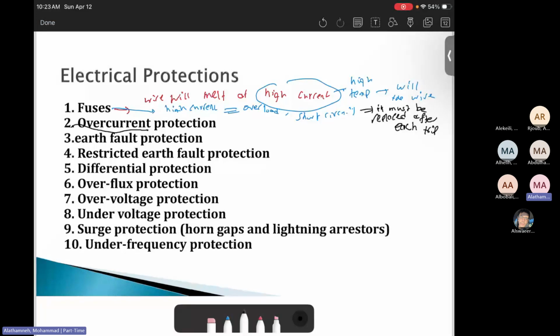There is a differential protection. We will again talk about overviewing the protection later, but differential protection is used in the transformer a lot. Like here is the transformer. Then we detect the current going in here, how much the current is. Then detect the current going out. Then put them in per unit. In per unit, they must equal each other.